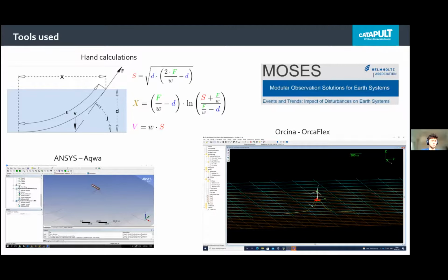But one of the most common pieces of software used in the industry for mooring analysis is OrcaFlex by Orcina, which has a great GUI and even has a Python API, which you can use to run a lot of batch analysis, etc. Whilst this isn't able to do diffraction analysis, Orcina also produced another piece of software called OrcaWave, which can perform all of the diffraction analysis and get RAOs for platforms.